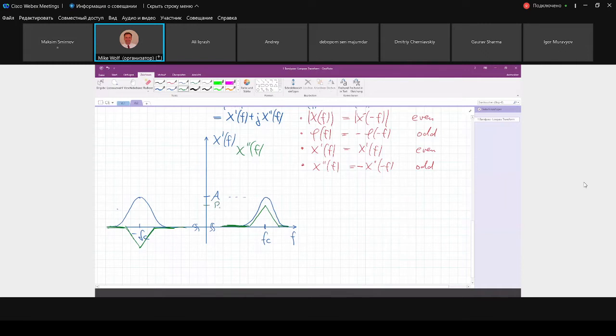Now you would say, it's quite easy to understand. If we delete the left-hand side, we still have the complete information, because we can redraw the left-hand side if we know the right-hand side. The idea of this transform, and now I show just this arrow, is that we do a transform from a bandpass signal to a low-pass signal.